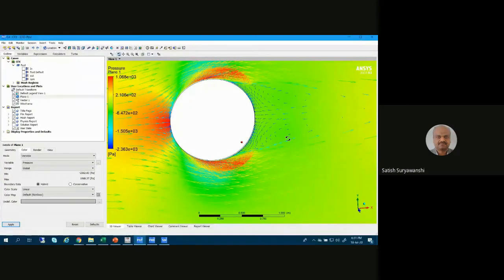Related to this boundary, suppose at the inlet condition we know the boundaries, and at the outlet we just mention the outlet pressure. Is it automatically solving the conservation equation? On the outlet boundary, we are just mentioning that the relative pressure is zero. So when the relative pressure is zero, the pressure build-up will be based on the zero outlet pressure. So it will be a reverse calculation. The drop will be taken into account. Yes.